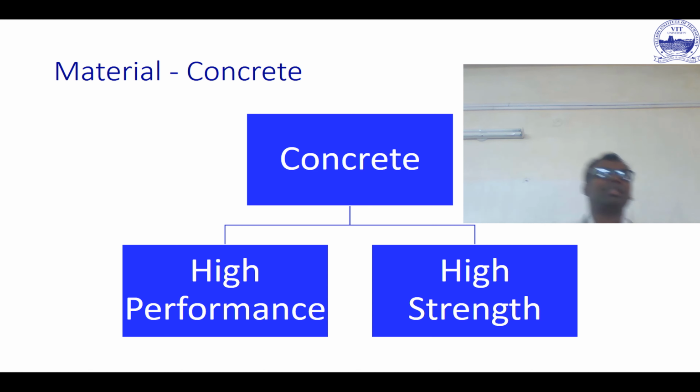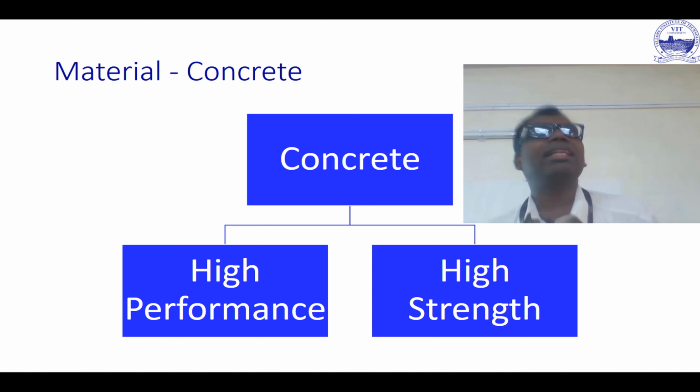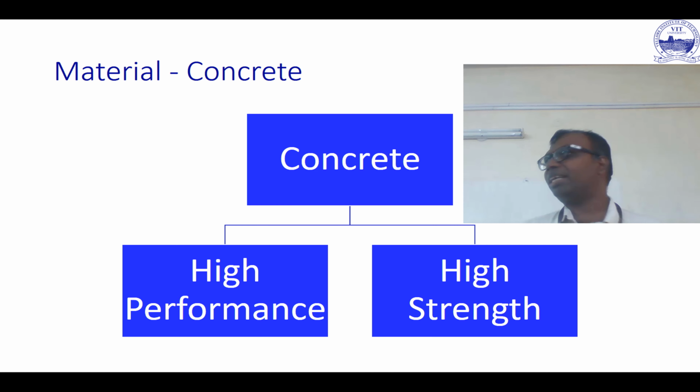So that's the thing. Here you got a zero slump concrete instead of a concrete which flows a lot. Again, the strength which it achieves is very, very high, and you also design this in a manner that certain desirable properties like reduced creep and reduced shrinkage of concrete are there. Thermal effects, of course, you cannot do anything, okay, but you can definitely play around with the other two, like reducing the creep, reducing the drying shrinkage.